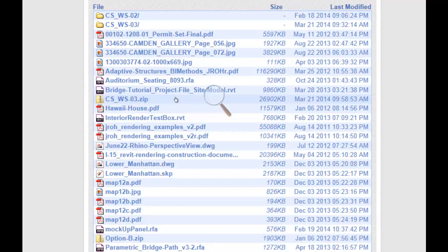If they've made AutoCAD drawings of these sections, can they import that, or would that be an unnatural marriage to their model? You can. If you have a CAD section that you've already done or some kind of details, you can bring that into Revit, and you could either try to draw on top of it again, or you can keep it in there if you want, but it'll lose some connection with the model if it's not a Revit object. Gotcha. I can cover that.